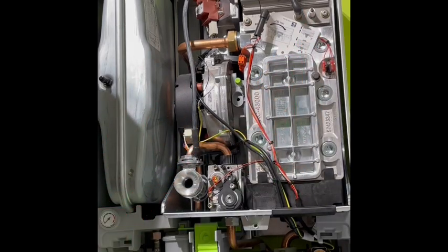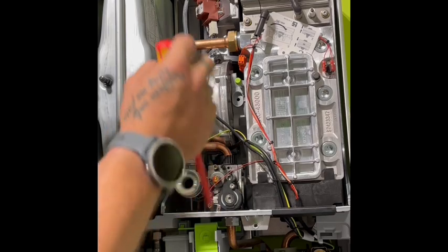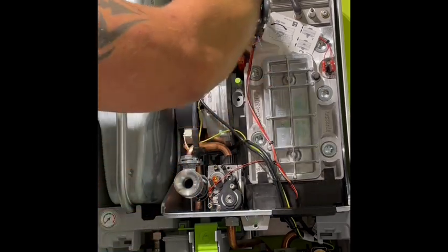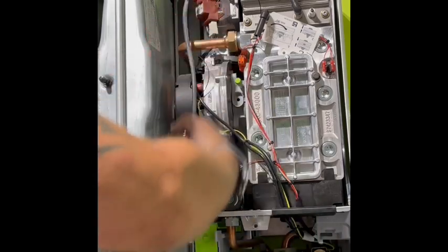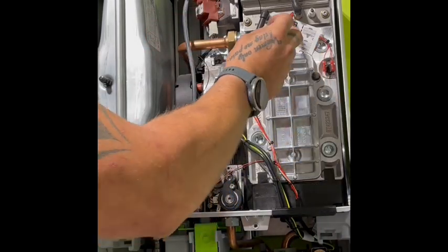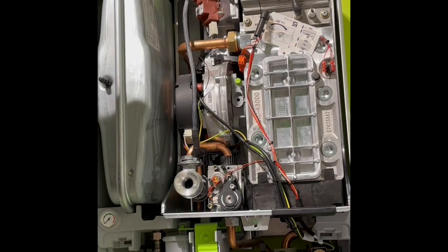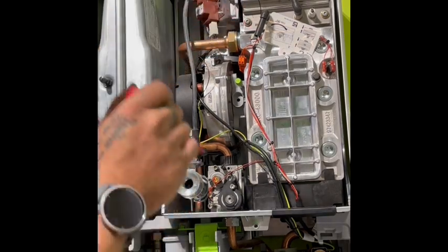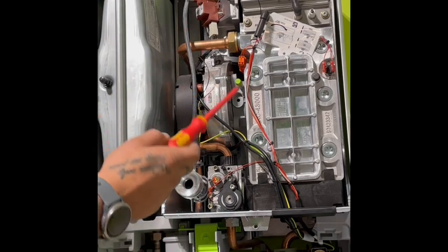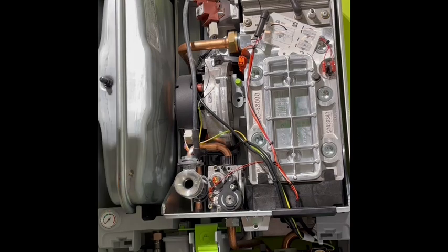On particular models of boilers, like the Baxi Solo Plus HE, electrodes are on the front of there and there's a big insulation panel on the inside. If that insulation panel gets wet, that will also cause the spark to arc out against the water in the insulation panel. So we can take that out, inspect them, isolate the gas and run it through the ignition sequence and hold those and make sure the spark is a good strong spark and everything looks okay with the electrodes.